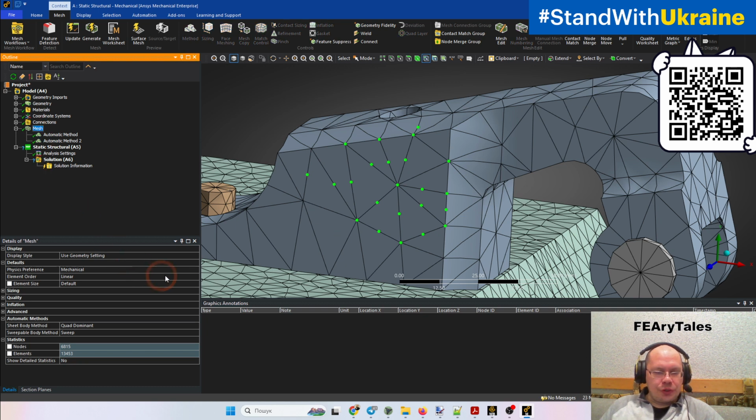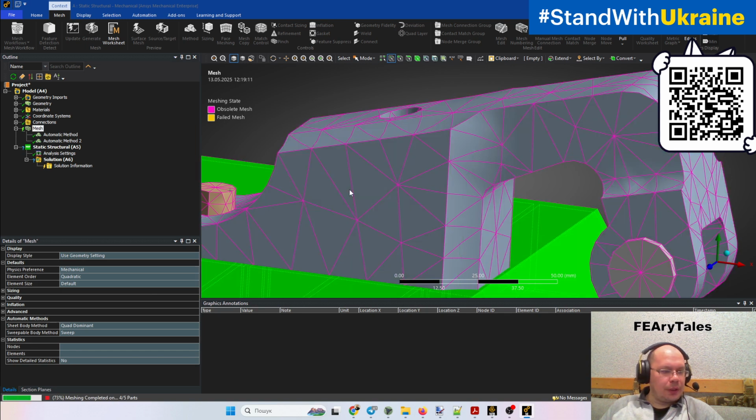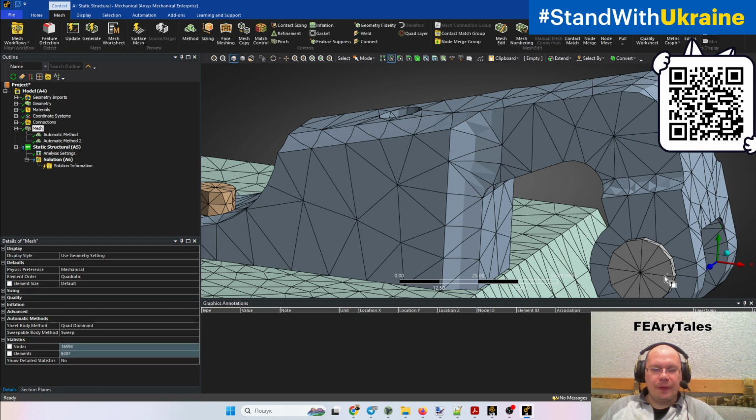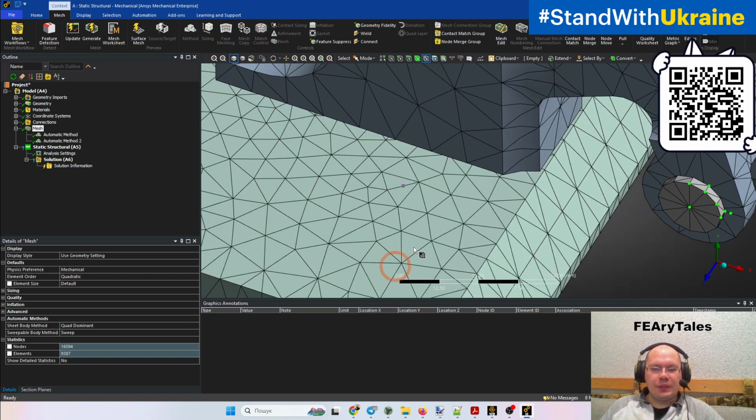And even if we change here from linear on the global to quadratic and recalculate our mesh, this object will have the quadratic element, but those objects have only linear without mid-sides, as we created here. And for this body, we didn't create any additional preferences, so it uses global settings.